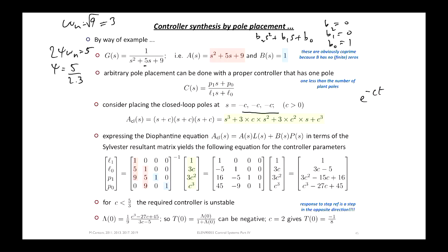We know some closed-loop transfer functions inherit zeros at the locations of poles. And so we're going to get a right half plane zero in our closed-loop transfer functions because of the pole of the controller being in the right half plane. So I'm trying to just highlight the pitfalls of looking at these things. You can get some unexpected stuff happening, and it's because all of the attention is being focused on where the closed-loop poles are. We're not paying any attention to any other aspect of the closed-loop transfer functions. So there's already something weird happening.